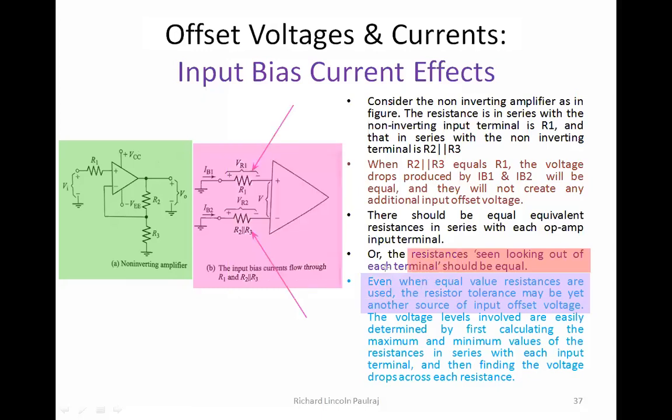So now there is another problem for us. What problem is it? Not only maintaining the same resistances, but we should also maintain the same type of tolerance. So there should be a gold band on the top one, and at the bottom one here also, I should have a gold band, right? So the same level of tolerances also should be maintained.